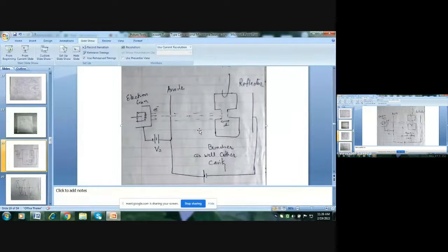So when you perform the experiment, you have to change this reflector voltage such that we get maximum power output. That means at this instant, the highly dense electrons interact with the cavity in retarding mode and we get output. Otherwise, the electrons interact with the cavity in accelerating mode and power is extracted by the electrons from the cavity, and the electrons get heated up and may burn out. So we have to be careful about this condition.